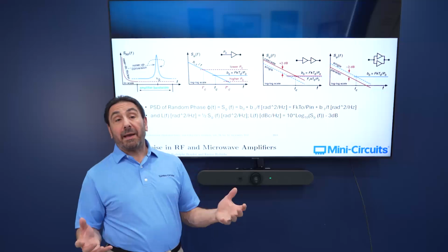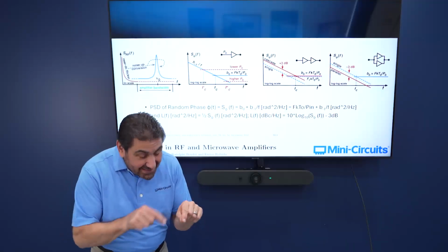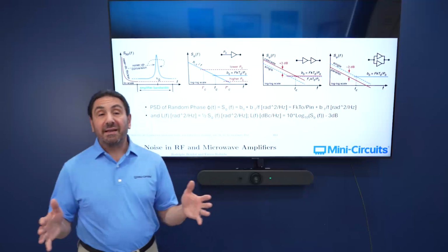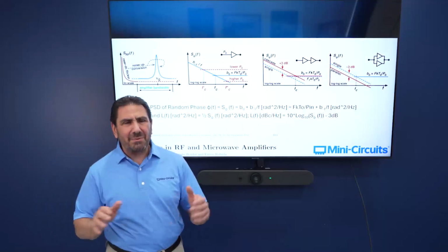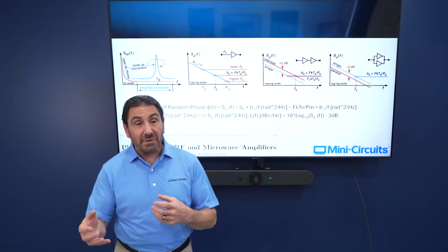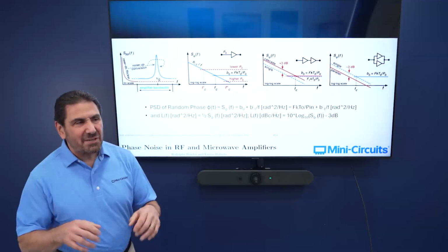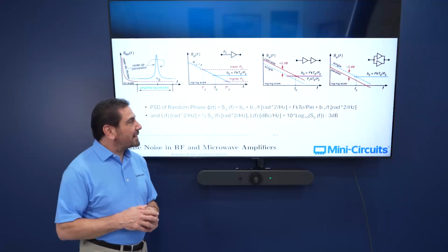Maybe if it's a bare die, you can get a blurred image of, oh, I kind of see, it's a cascade. It's got 3 common source stages in cascade. Maybe it's got feedback, maybe it doesn't. Maybe it's reactively matched. Oh, I see this one's got line couplers. It's a balanced amplifier. So you can get some indication by looking at the bare die.